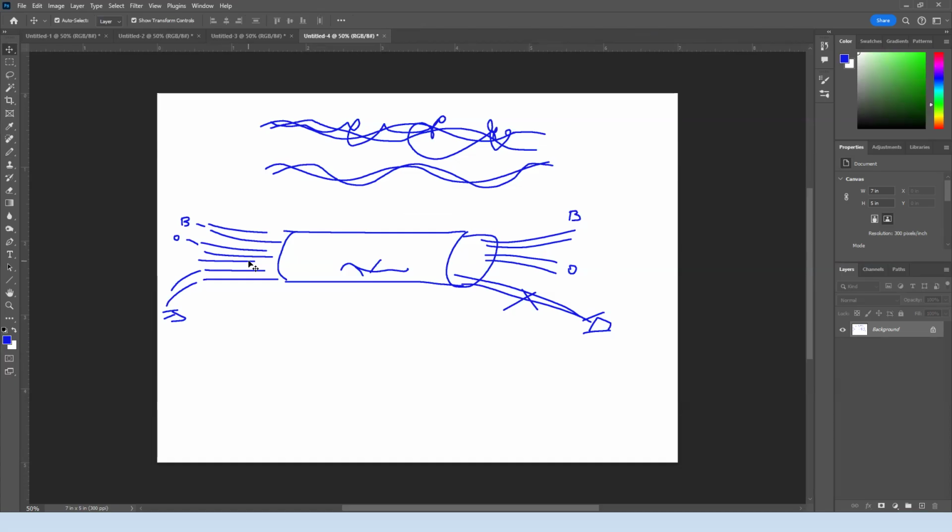So what the techie would sometimes do is split the pairs. They would find one bad pair that was already marked as bad, and another bad pair, and hope that just one of those conductors is broken and the other is intact. So let's say this one is working, and that one is broken somewhere.